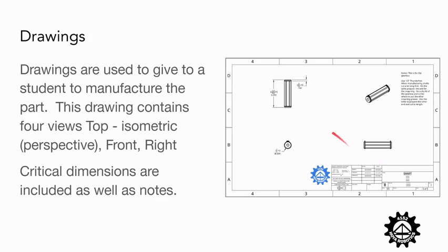So if we have a three-dimensional object, we'll typically have those four views. If it is something that is a kind of a plate, a two-dimensional object, we'll often just have the flat view of it. And then we have some critical dimensions. So those kinds of things. Now, I wanted to include a shaft view because it's really important that when we see the critical dimensions, we make sure to manufacture it.